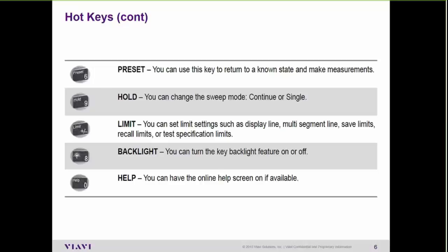So you can put limit lines across the screen that allow you to set this device up, say a noise floor measurement, and if at some particular point in time you're getting a loud spike or spur that comes into it, you can set a limit line on your display, and if that limit line is broken, you can have the test set automatically log data onto the USB stick.